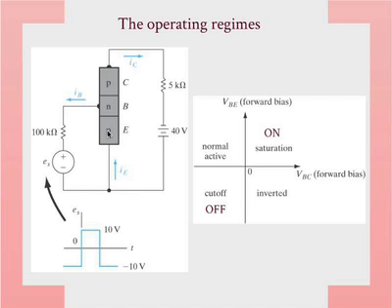So if I switch the collector and the emitter, in other words, if I make the base emitter junction reverse biased and the base collector junction forward biased, then I can have hole injection from the collector to the base to the emitter. It's just an inverted situation. You don't need to worry too much about it, but for our purposes it is exactly the same as active operation. So all you really need to remember for the regimes of the BJT is just three situations here.